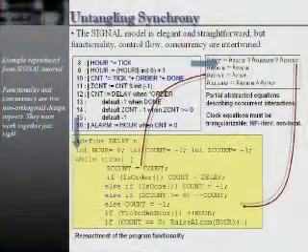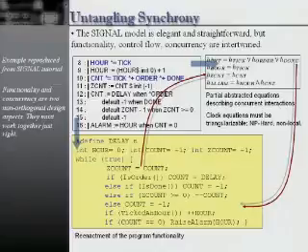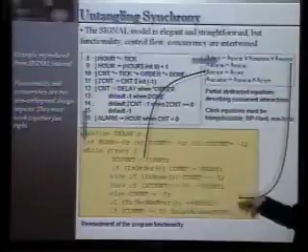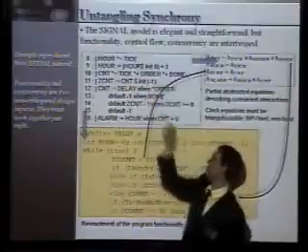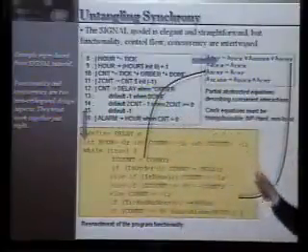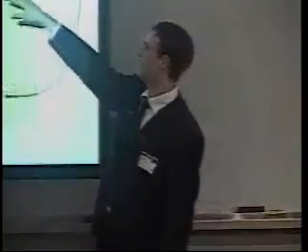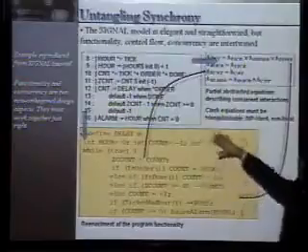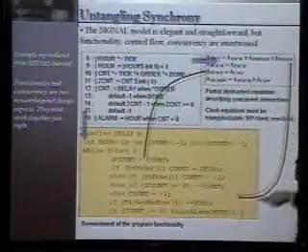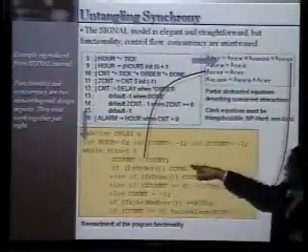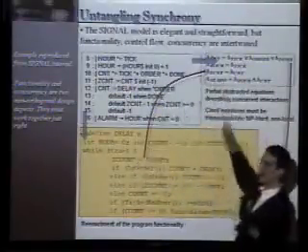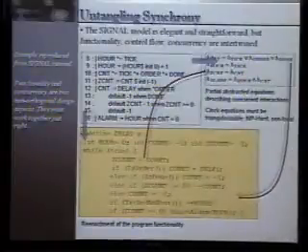Now, it also means these sets of equations over here, which link together the clocks of all the variables. It gets even more complicated because the way that I wrote this C code, I wrote it knowing what these clocks did. For example, there's a clock equation here in bold saying that the clocks of essential key signals, order, done, and tick, are all linked together. The clock of the counting signal is the union of all of these. If I hadn't put that in there, I wouldn't have been able to write this. So I added this clock constraint that allows me to interpret the functionality this way. The functionality also implies equations on the clock side. So these views are intertwined.